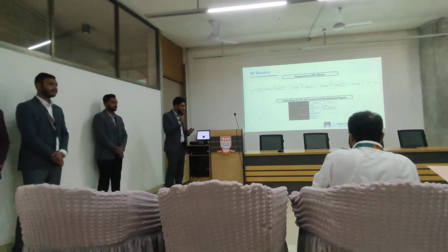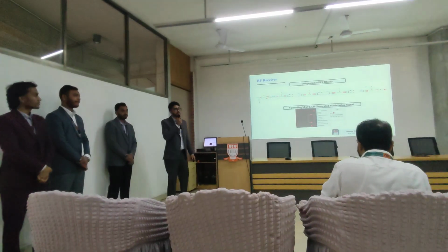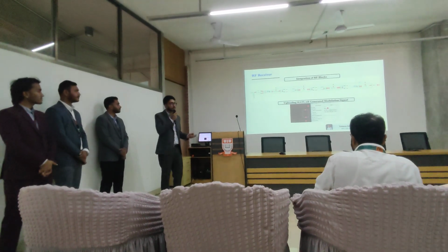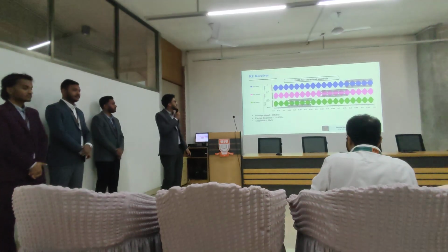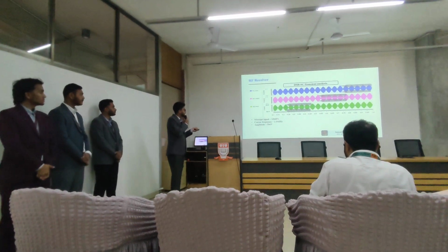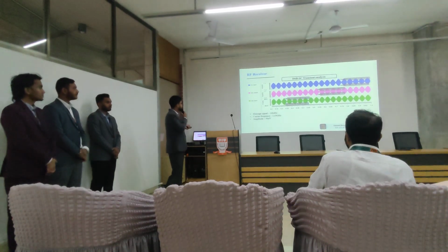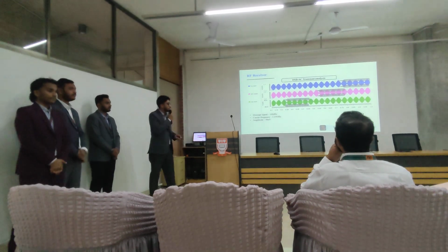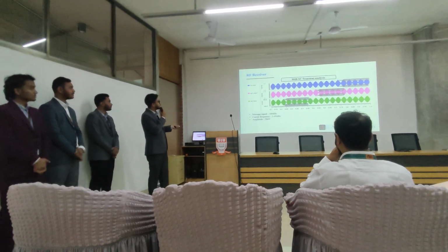Thank you, Dawar sir. Now I will discuss the total result of our RF receiver block and the functionality of our receiver. First, we move to the DSB-SC carrier transient analysis. Here we use a message signal of 10 MHz, and the carrier frequency is 2.45 GHz with a 50 microvolt amplitude. Let's see the graph of how the signal moves through each individual block.